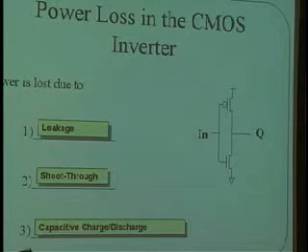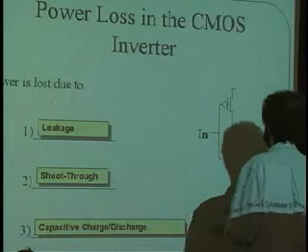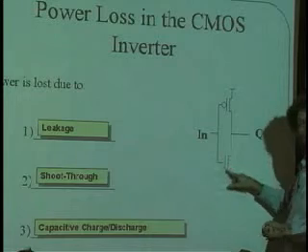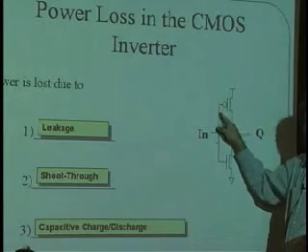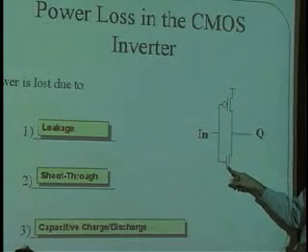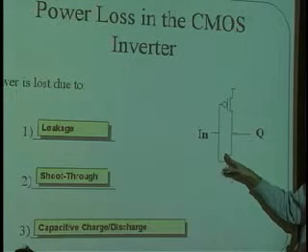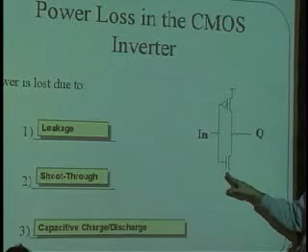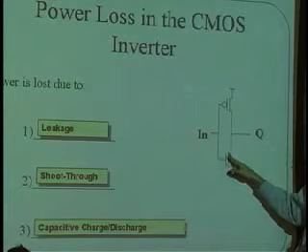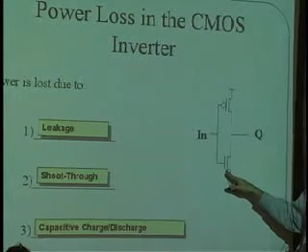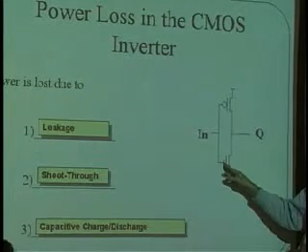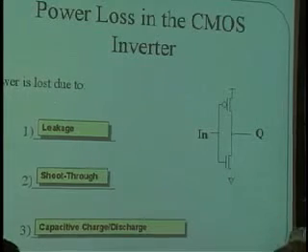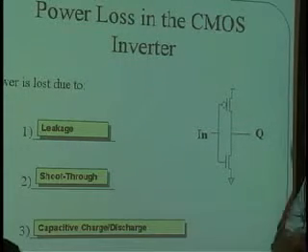And the capacitance of the next stage is primarily the capacitance formed by the gates of the transistors of the next stage. Because if you remember, these gates are formed from a semiconductor of some sort, glass, which is an insulator, and then the channel. And that plate structure is the form of a capacitor.